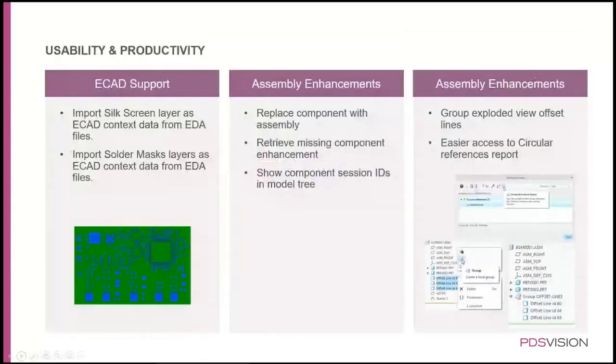Then some general usability and productivity enhancements. We have enhanced our ECAD import support, and nowadays the silkscreens and the solder mask are in there as well. Previously they were non-existent. This just means that all the markings for your PCB plates are there, and also the areas that will be covered with the protective pads are also in there.